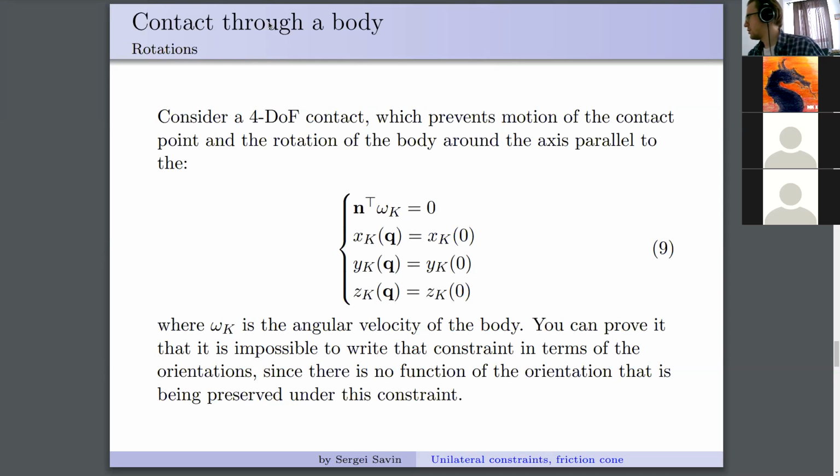If you ever skated, you know that you can arrive at any position on the skating field, but you cannot move sideways. You just arrive using direct motion, maybe backward motion, stuff like this. So that is another example. This is what they call non-holonomic constraints. And this is why, because you cannot integrate it to achieve an expression in terms of q. You can only have an expression in terms of q dot and q.